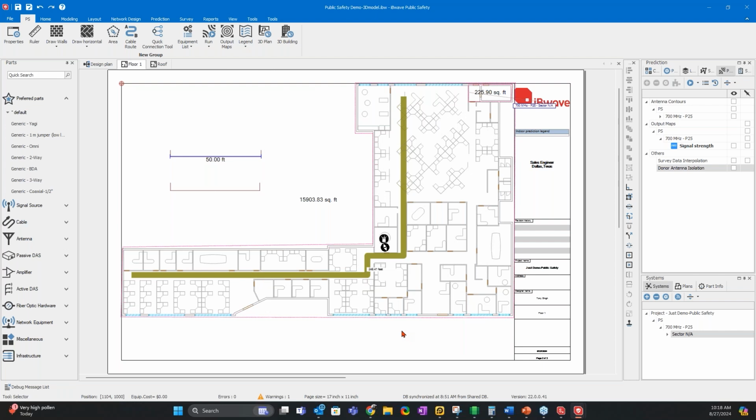So if you look at the area of this picture and ask how much you need to cover, based on my ideas, I think 2 or 3 APs can cover this area. Now, how can 2 or 3 antennas cover this particular floor? How do you know that? Sometimes it comes with practice. If you're new, you can just place one antenna, run a prediction, put another antenna, run a prediction. But in my example, I can tell you, and most design engineers after a few designs will say,